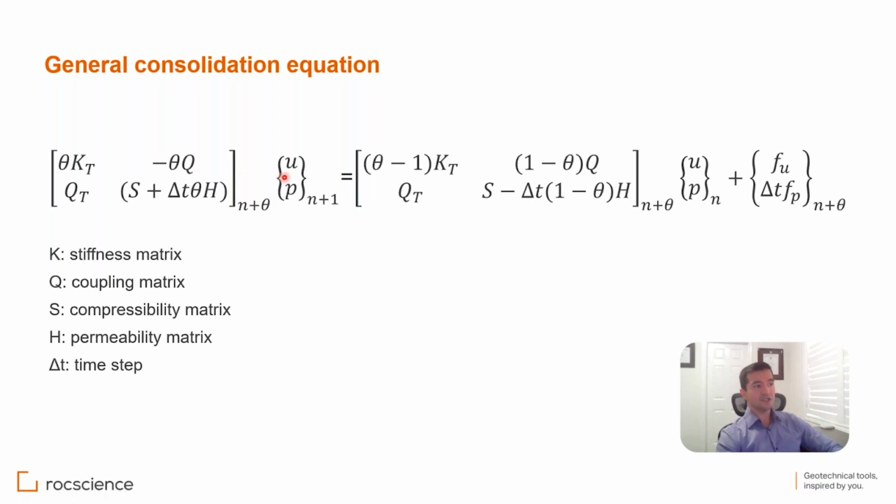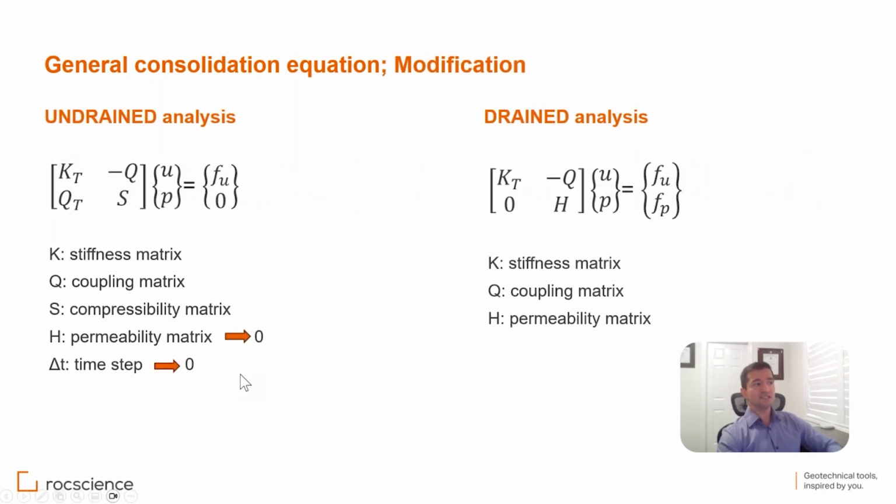This is fully coupled, so you have to solve for both displacement and pore water pressure at the same time. Solving this system of equations is quite expensive in terms of computation. Now we have a simpler version of it, if you would like to only deal with undrained analysis or drained analysis.